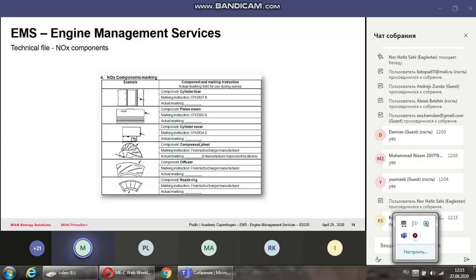You can just replace. But when you, with your chief access code, change your Pmax to say 10 bar, or PI offset by, let us say, 5%, 6%, then naturally the parameters will vary. Your NOx will change. But you must understand that with the chief engineer's password, there is absolutely no need to worry because you will not violate IMO MARPOL Annex 6. With your passcode, you can only go to a certain limit. Beyond that, you cannot go. So don't worry, you will not violate the Annex rule at all.